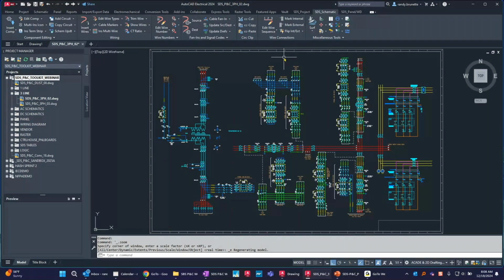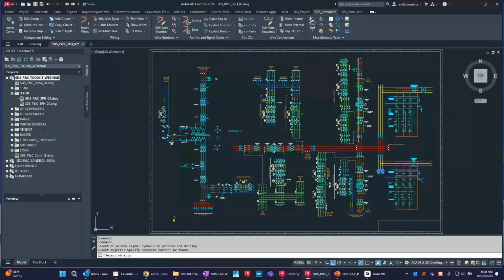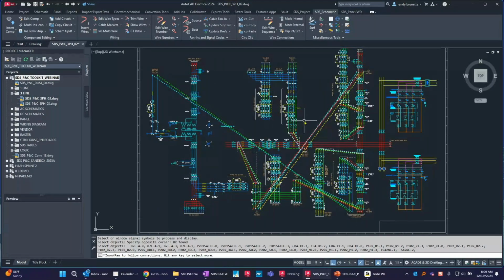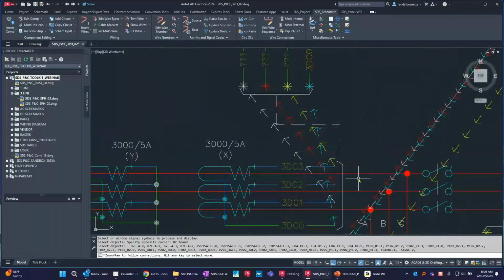Another tool I'll show, again, kind of a simple one, is Show Signals. This one comes in, and in a drawing where you have source and destination arrows moving around the drawing, you can select the drawing or parts of the drawing and see visually where those signals are going. If I zoom in on one of these spots up in here, you can see there's a source marker at the end of this wire, and there's a destination here. So the wires are ending here and then continuing on up into the next part of the drawing.